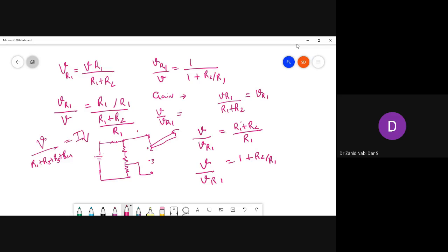So at knob 1, it moves a little slowly. Then another knob comes into play, switch 2. So it gets connected over here, and this is now not into play. In that case, it is R2 R3 plus R4. Current gets slightly increased. Then with the next switch, there would be only R3. Then there's the final switch, so V by R4. Only V by R4 means current is very high and it starts to rotate at a faster rate. Now you got my point.